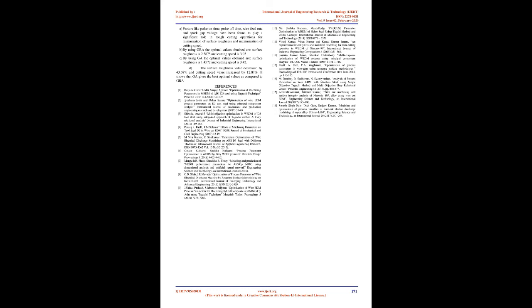These regression equations are copied in the MATLAB software. In MATLAB, the script files are written for the regression equations. Genetic algorithm technique is selected by using OptimTool in MATLAB software. The multi-objective optimization is done for both surface roughness and cutting speed by combining corresponding regression equations. The optimal process parameters are given in Table 9.